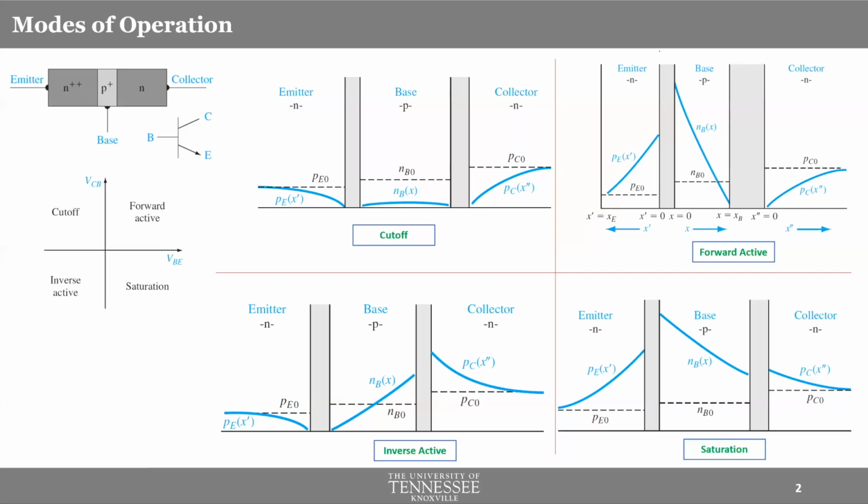Now let's try to examine whether that is the scenario here. This is forward bias, and this is the thermal equilibrium level. And you see at the surface, at the emitter base junction, you have higher than what you had at zero bias because you have a forward bias, by the way. And that's not only true for the N region, that's also true for the P region. See, whatever degree of minority carrier you had, now you have more than that, much more than that, because you have forward biasing. And by the way, how did that happen, right? How did that happen?